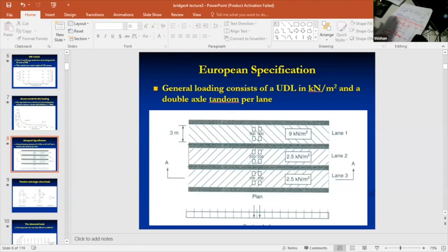You get a grillage, which is a frame of horizontal members subjected to vertical load. So basically, by looking at this, you can create a grillage and apply the loads in a reasonable manner, and then run it, and then get the bending moment. And you have to get the most critical bending moment. So that's the procedure. And the first thing is to create a grillage.